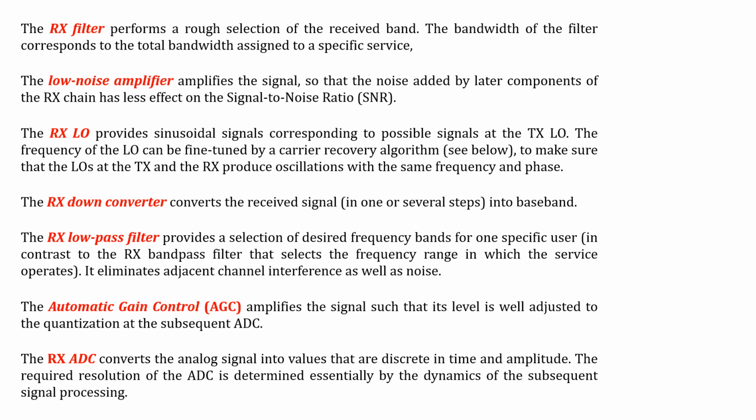However, the subsequent parts that we are going to see will add a sufficient amount of noise to the received signal. My signal has already undergone quite a lot of noise when it propagated through the channel, and now each and every component of the receiver chain will also add certain noise. So the signal should be strong enough to deal with all these subsequent stages. That is the reason why low noise amplifiers are used as the second component, where all the signals are amplified even before they are sent to the later chain of the RX circuit.